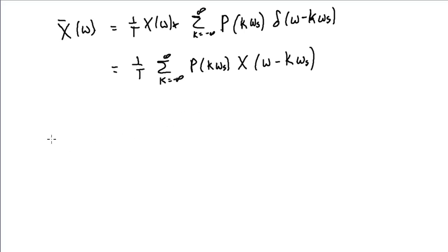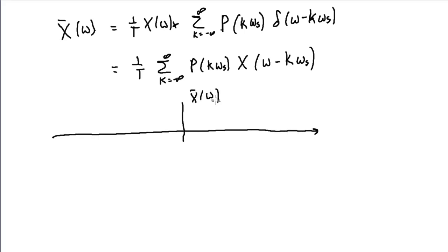So again, as long as the sampling is at a rate greater than the Nyquist rate, what I'll have for X-bar(omega) is again these spectra, from minus B to B, that now repeat at omega_s and 2 omega_s, but now the heights will be different.